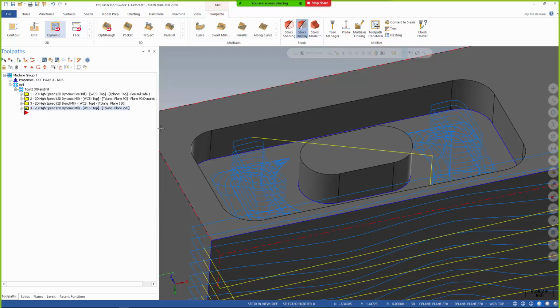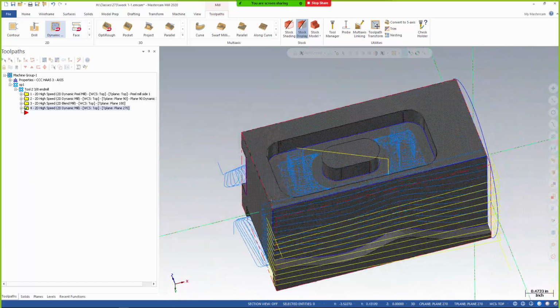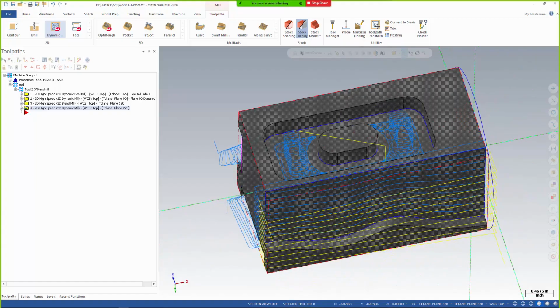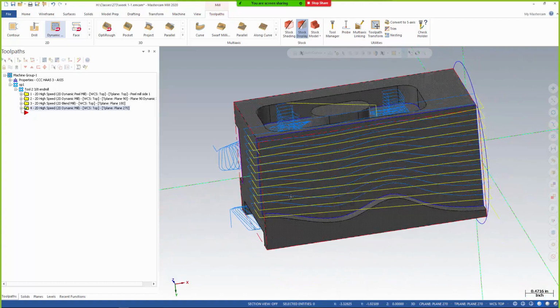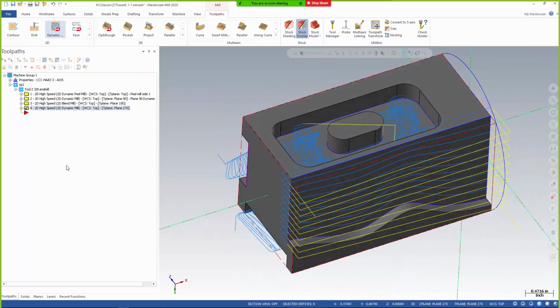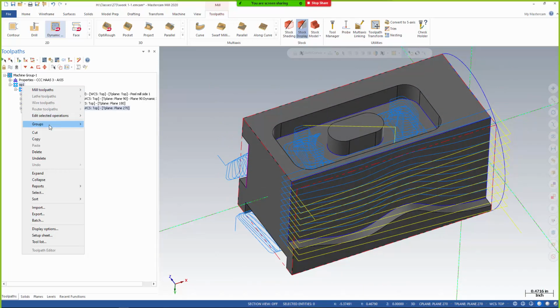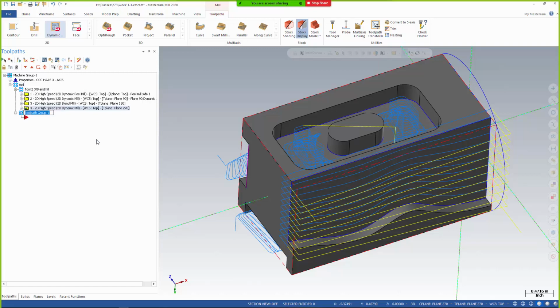So from here, since that's kind of roughed out a bit, if I wanted to change the tool size and do basically the same thing, one of the things I could do is right click on my number one operation, come down to groups, new toolpath group, and this is going to be, say, tool 3, and this is a 1/4 inch.